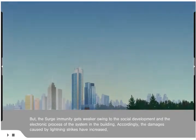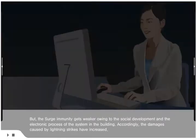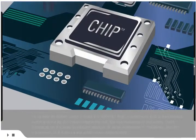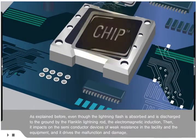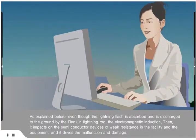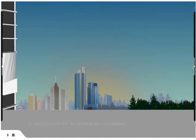But the surge immunity gets weaker owing to social development and the electronic processing of the systems in the building. Accordingly, the damages caused by lightning strikes have increased. As explained before, even though the lightning flash is absorbed and discharged to the ground by the Franklin lightning rod, the electromagnetic induction then impacts the semiconductor devices of weak resistance in the facility and the equipment, and it drives malfunction and damage in the building where the lightning rod was installed.